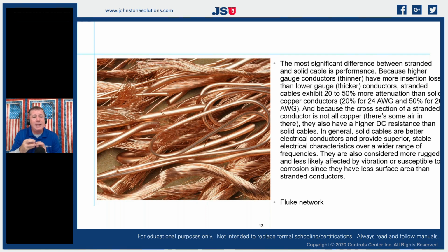So a lot of times the equivalent wire between solid and stranded doesn't actually pass the exact same amount of current. We can typically flow more current through the solid conductor than we can with the stranded, just because the stranded doesn't have the same amount of surface through it.